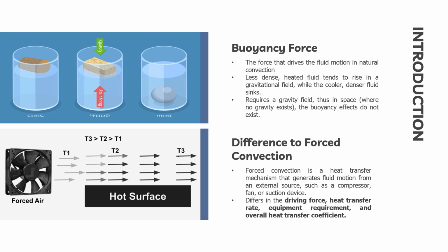When a fluid is heated, it expands and becomes less dense, and due to the buoyancy force, it rises. This upward movement of the heated fluid creates a pressure differential between the heated fluid and the surrounding cooler fluid. Essentially, the buoyancy force tries to equalize the pressure difference caused by the density variations due to temperature changes. It's also important to note that the buoyancy force requires a gravity field, so in space, where there is no gravity, the buoyancy effects do not exist.